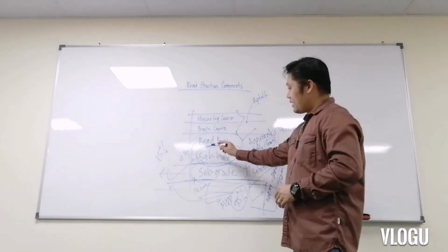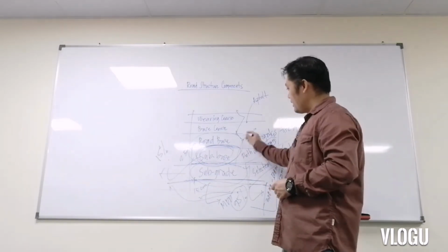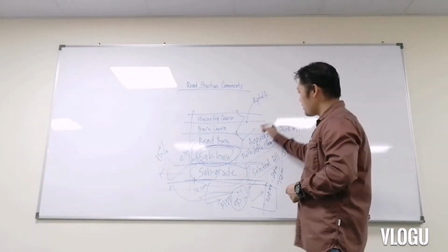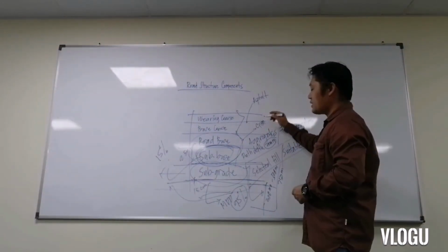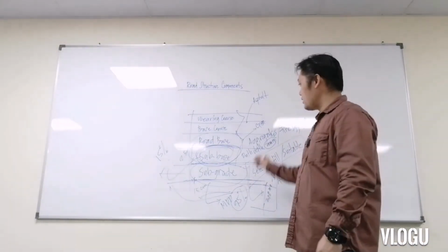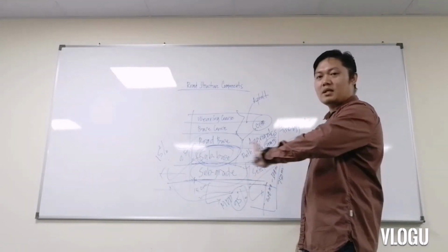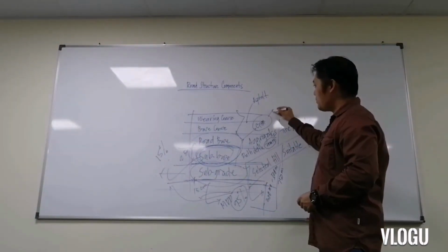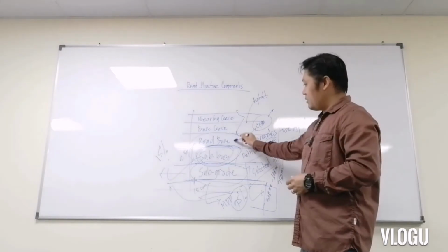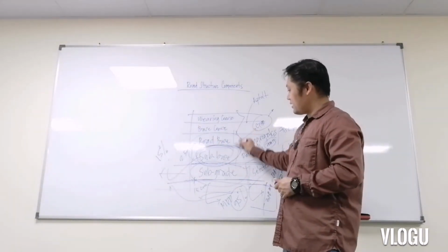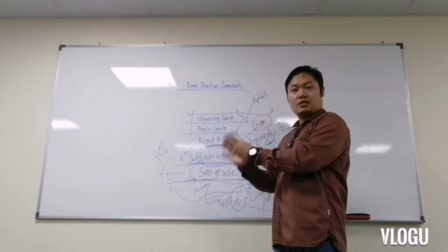And right now, after we completed the subbase, we're going to proceed now to the road base. In some other road design components, sometimes instead of road base, they are using CBM, known as cement bound materials. Well, anyway, once again, it depends on the project requirements and project specification. Right now, some of the people are still studying the parameters of the CBM. So again, on the road base, the thickness will be based on the design. The road base will be spread using a paver.